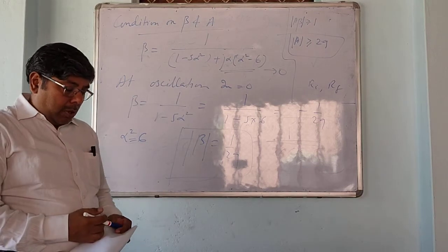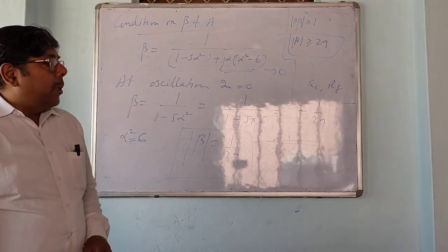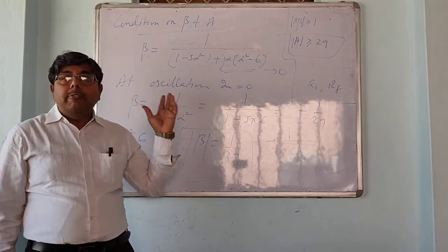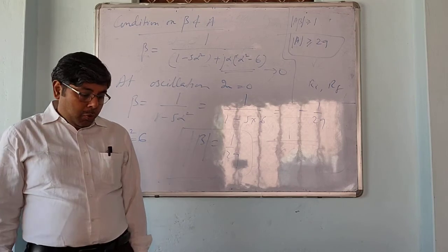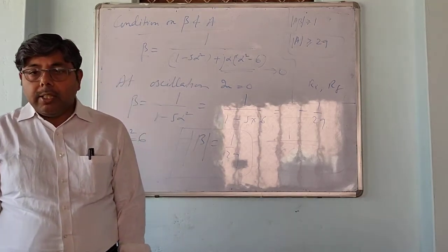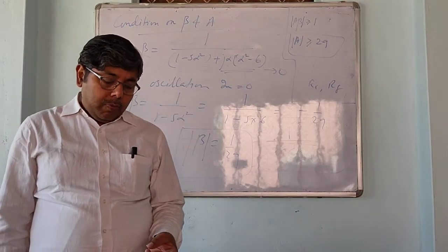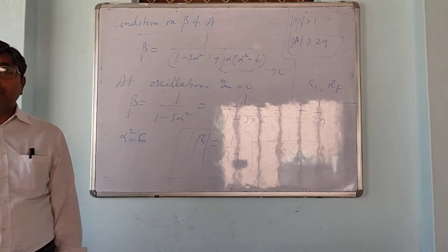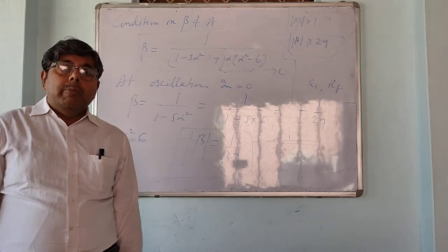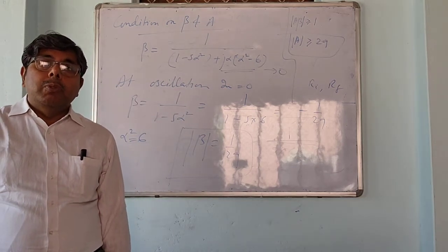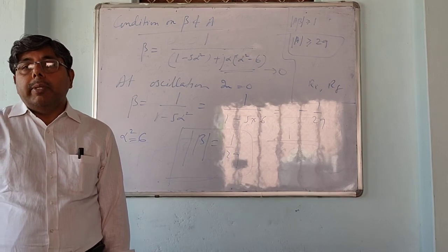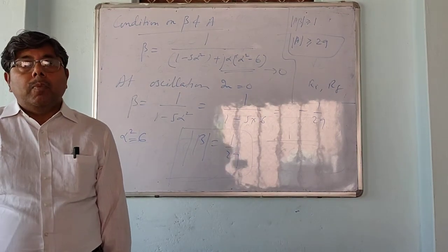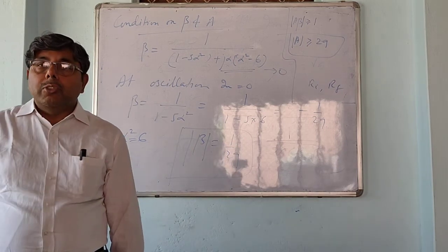So this is all about the operational amplifier based RC phase shift oscillator. So the rule is simple. First draw the circuit of the oscillator, then draw an equivalent circuit to find the frequency of oscillation. Simply apply KVL for 3 loops, write the equations in matrix form, then calculate beta and put the imaginary part equal to 0.